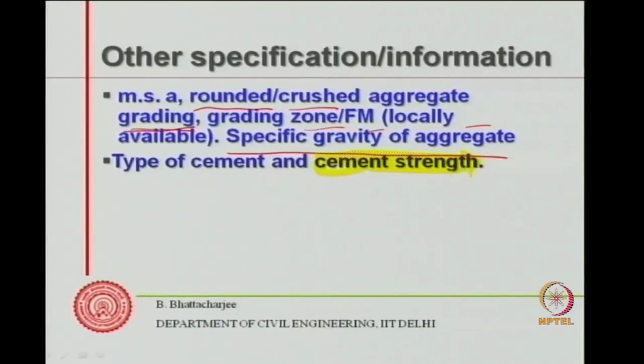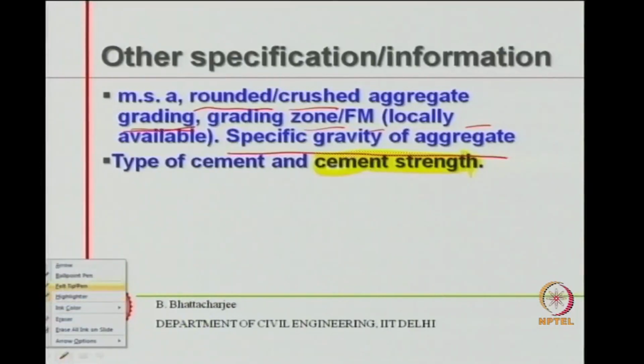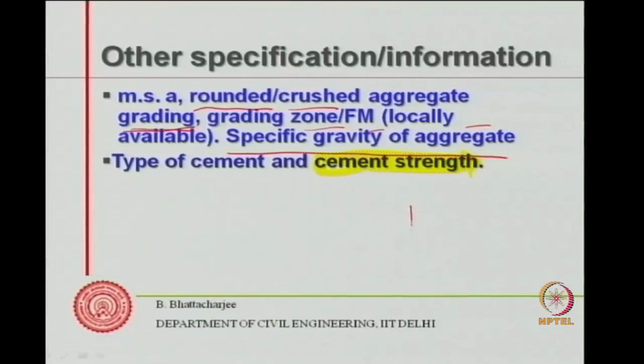In fact, earlier Indian standard was using this cement strength as an input, but now it is not a necessity in Indian code, that is IS 10262. This is not a necessity anymore, but earlier the code was using it. So that's why this appears here, but by and large we don't need this information now.